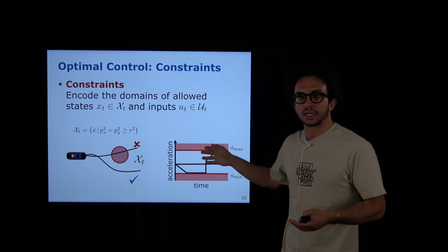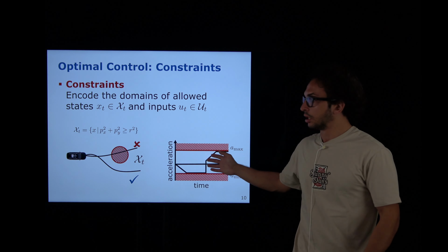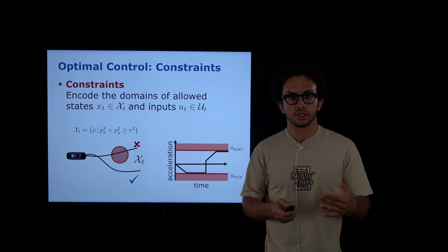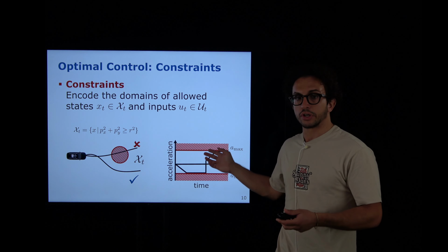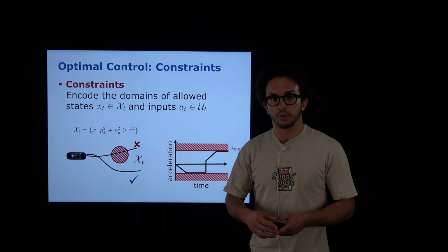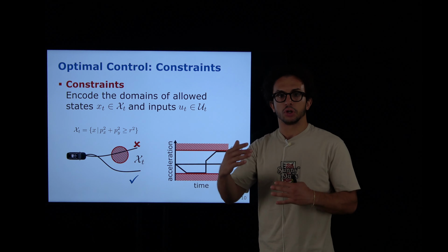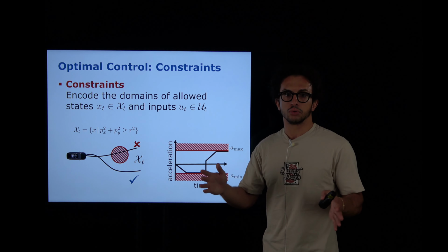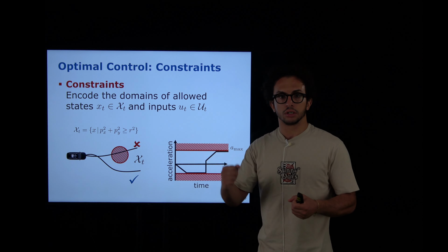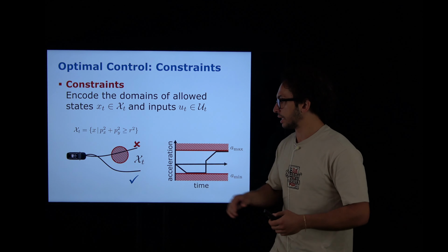So this is a constraint that, for example, in the case of the PID, we know it's very dangerous because we know that when we saturate the control, the actuator's signal, we could get into the wind-up problem. Well, we just have a constraint that says, well, you cannot go beyond that. This is the best you can do. This is the stronger you can do something, the most powerful you can accelerate or anything.